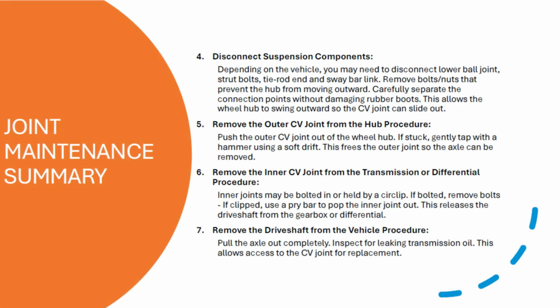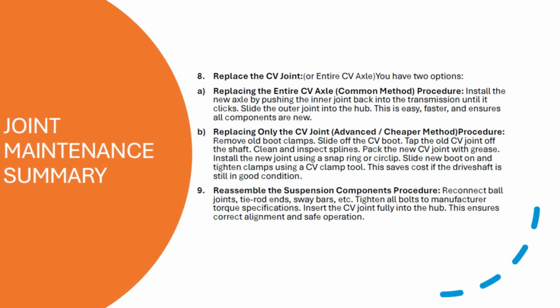For warranty claims and diagnostics, accurate documentation is vital. Always photograph damaged boots, document specific noises heard, and note the precise location of any observed grease splatter. We now review case studies to apply what we've learned. Analyzing real-world failures helps in identifying misdiagnoses and improves the accuracy of future repair and warranty assessments.